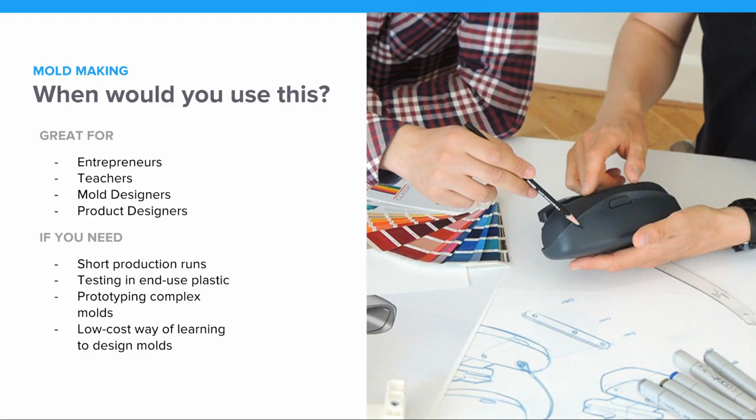I'd also like to throw out for mold designers, there's a benefit here where you could offer a lower cost alternative to short run production for your customers. So let's say they come in with 150 parts, rather than doing 3 silicone casts or spending the money to make a CNC machine, you could just 3D print one mold and have it all done on that single mold.